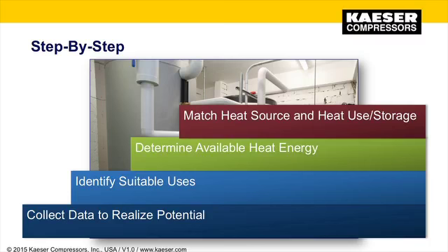Step 4. Now you match the heat source with the heat use or storage. You analyze the local conditions, the period of time the heat is being used or needed, the choice of components, the overall layout, and the calculation of profitability or return of investment.